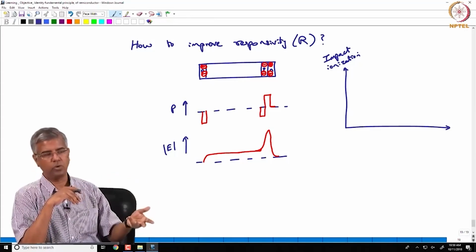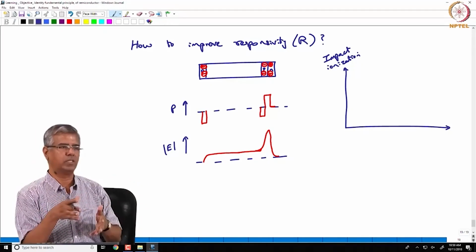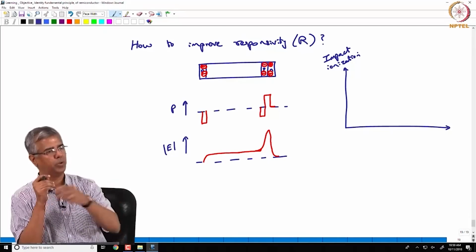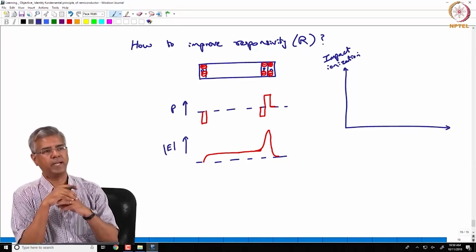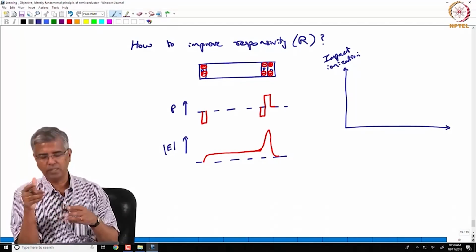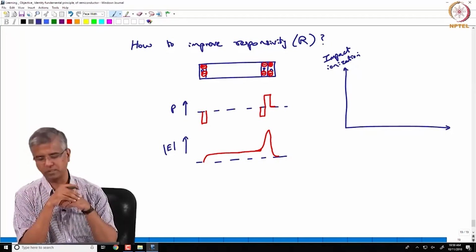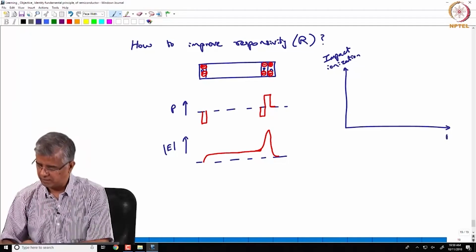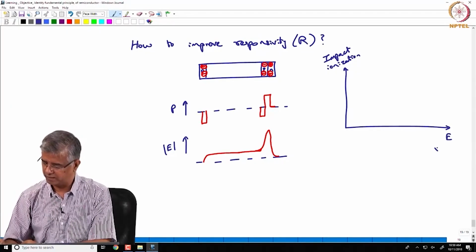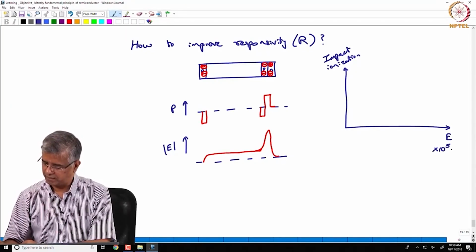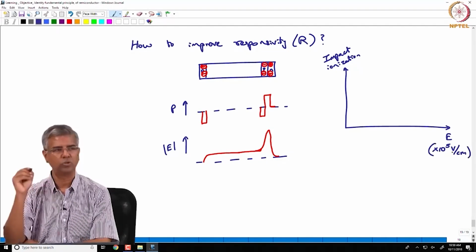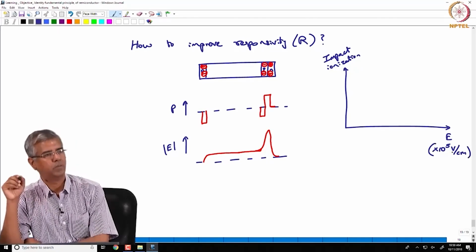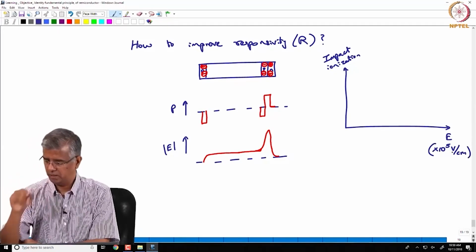And those electron hole pairs still carry a lot of this momentum. So, those can go and create an impact ionization on the neighboring atom and so on. So, this entire process can multiply. And if you look at the impact ionization as a function of the electric field, we are tracking electric fields in the order of 10 power 5 volt per centimeter, very close to the breakdown strength of the material.